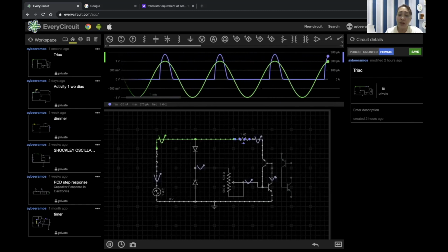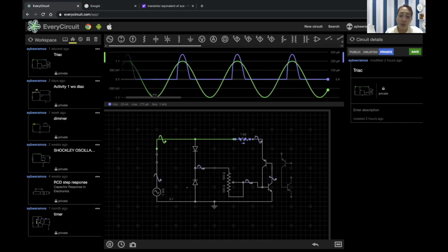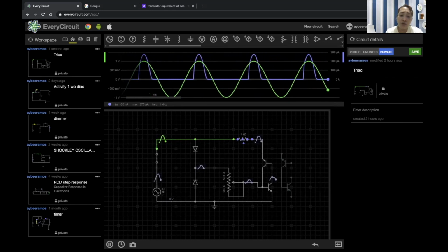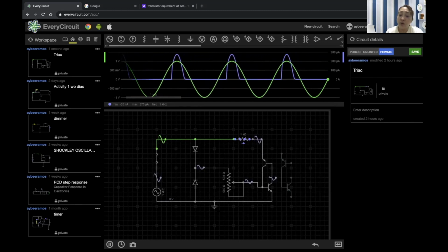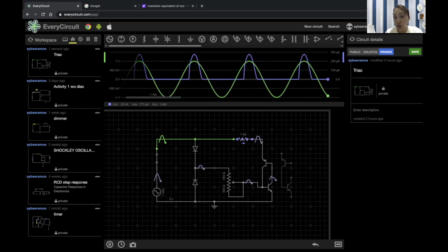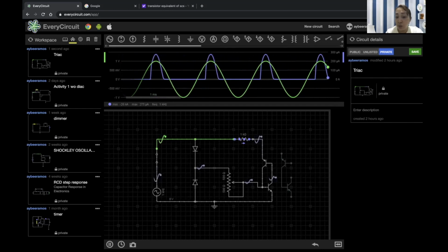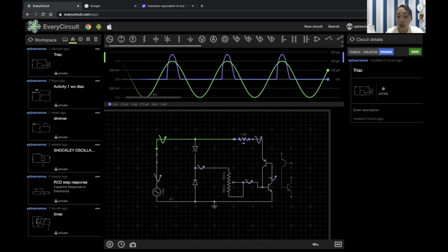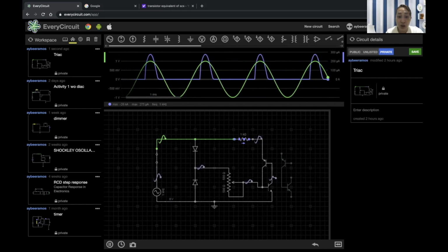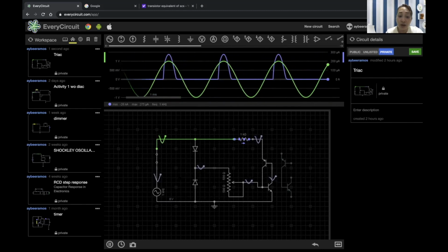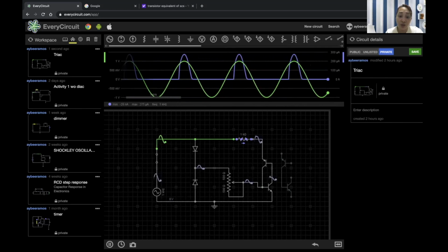But why, ma'am, is it not broken down? We have an AC supply and yet it is safe to use the SCR. Remember, we have diodes connected to the gate. That means our triggering devices are the diodes.